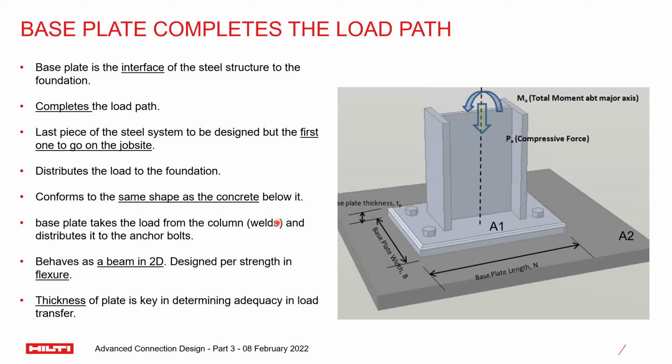As we all know, a load path is fundamental for proper design of any structure, and the base plate is a piece of this load path. It provides an even and smooth transition of the load from steel to concrete. Typically, the base plates are the same shape as the foundation. Since most foundations like spread footings and piers are rectangular, most base plates are again squares or rectangles, which helps in spreading the load into concrete.